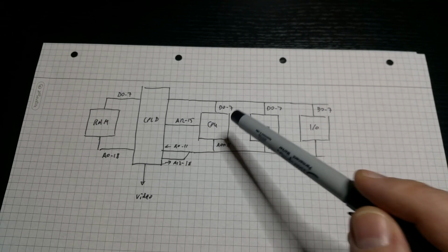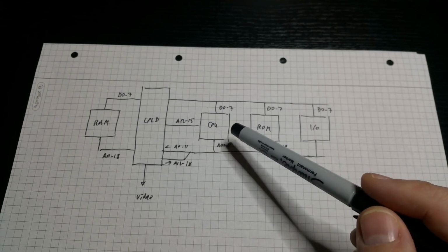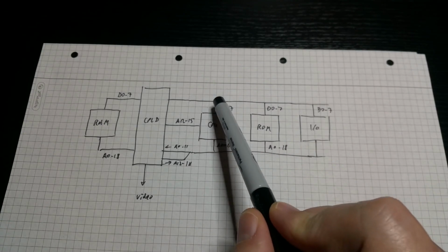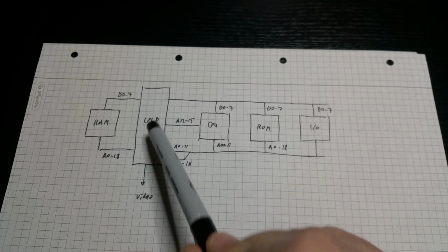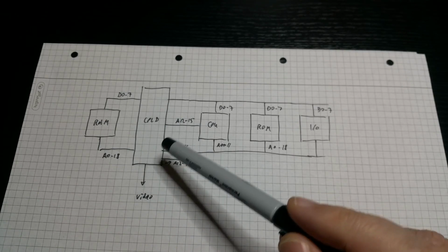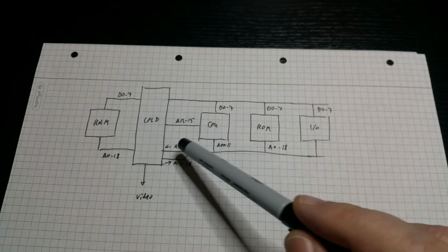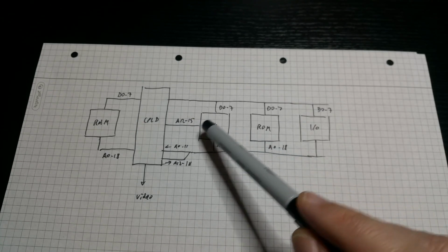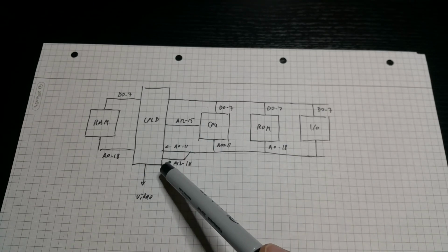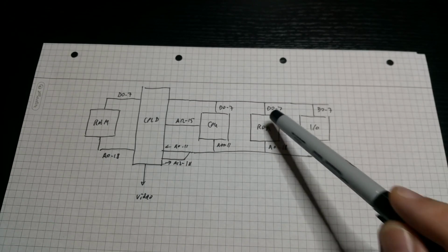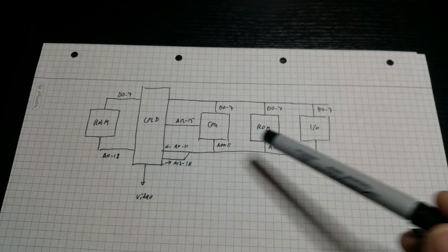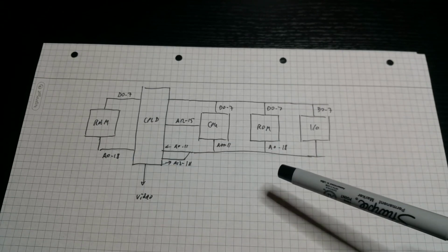So basically, if you look at the CPU, it's a 65816. It sends in the first half of its cycle the bank address to the data bus, which gets read in by the CPLD, which then does the mapping of the address ranges and so on. It also uses A12 to A15 from the CPU and translates them into appropriate RAM or even ROM addresses here. And that's basically it. It's really a very simple architecture.